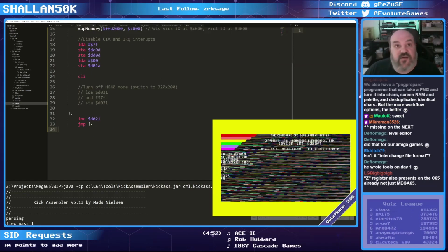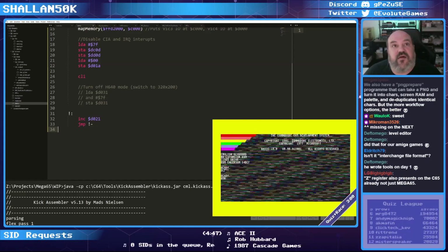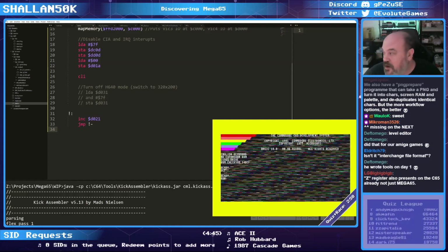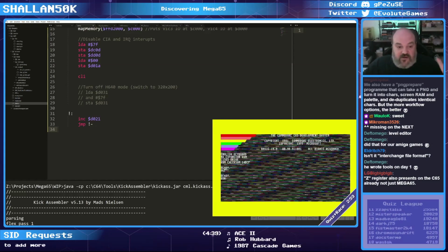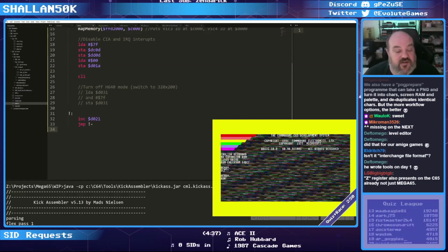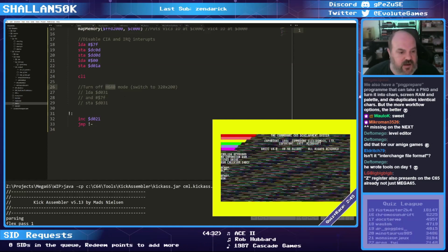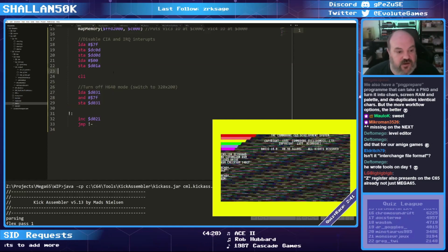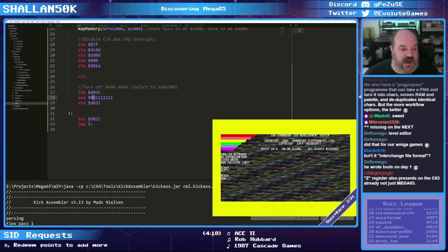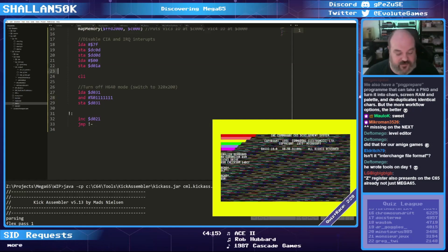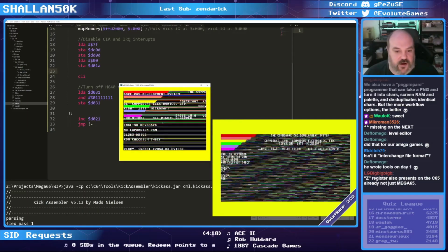You'll notice on the C65 and the Mega65, the default mode is an 80 column mode, kind of like the C128 80 column mode. So there's actually 80 characters across the screen. So the screen is 640 pixels wide, or it's called H640 mode. You can turn that off, and you can switch it back. By turning off bit 7 of D031, you turn off 80 column mode, and you switch it into 40 column mode, which looks more familiar.